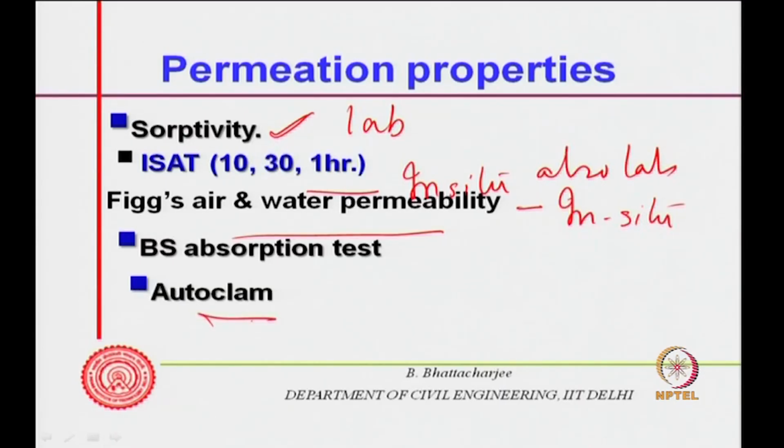There are a number of them, a series of them have been developed at different places, like this one in Belfast, this is the BS absorption test, this is also a BS test, sorptivity originally by Hall, etc. So, there are several other properties. There is one in Switzerland, some modification of this one, because this requires vacuum application. So, without the vacuum application.